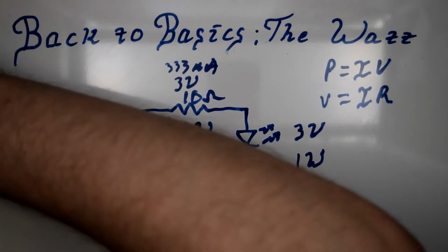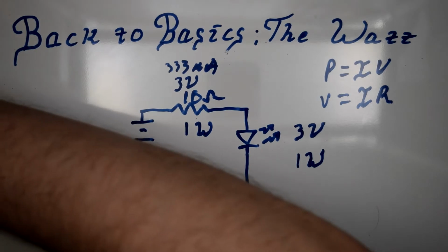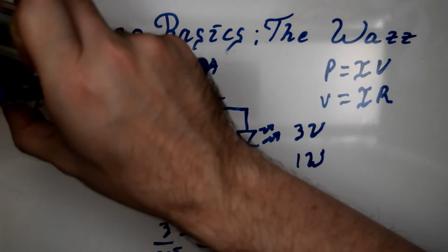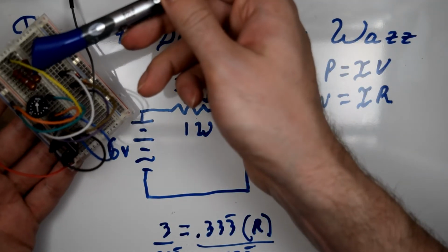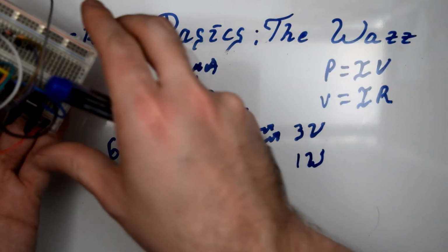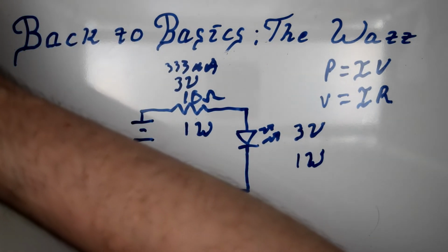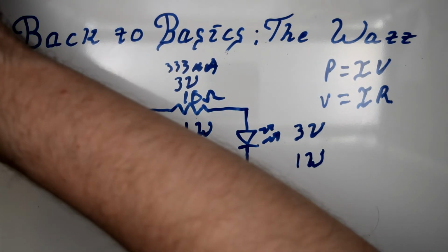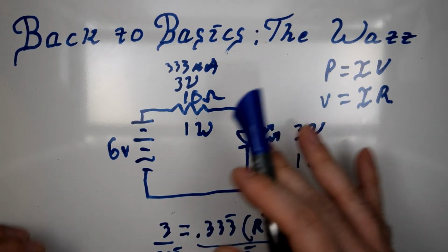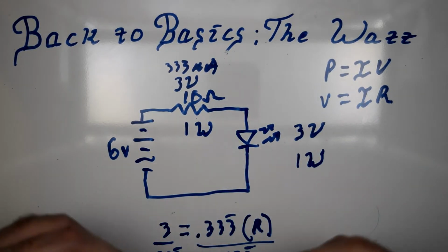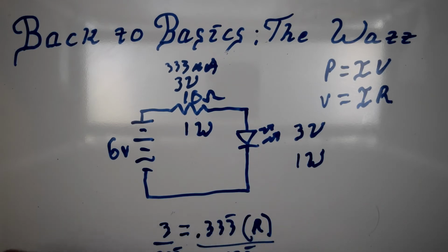Because, and let me grab my little proto board here that's currently powering my LEDs. These guys right here, these big honkin' resistors, those are 2 watt resistors. They're actually much bigger than they need to be for that circuit. But I had them on hand, so I went ahead and used them. Now, a 1 watt resistor is going to be about 60% the size of that one. And if we dissipate 1 watt through a 1 watt resistor, it's going to heat up to about 100 degrees Celsius.